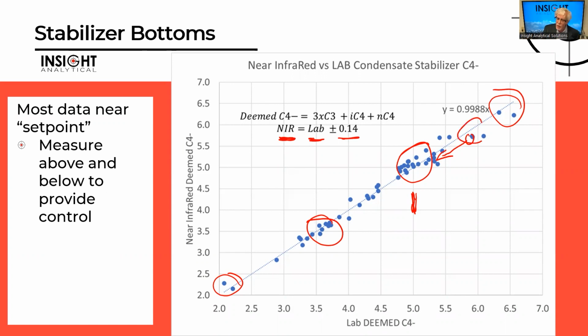I'm purposely going to run up here for a little while and balance that out again. So I know that I produced 3,000 cubic meters that only had 3.5% butane in it. I'll make sure that I run high on butane for a little while and let that average out at the end. Then I can produce a bit more volume.